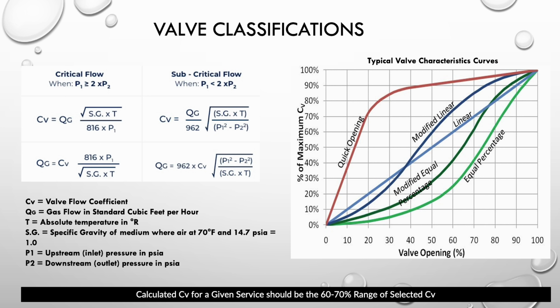Subcritical flow, which mostly you're going to see in liquid flow. Again, liquid flows can still have sonic flows, but for it to reach that point, the pressure drop has to be significantly high. It's something you wouldn't get accustomed to seeing in industry. So normally speaking, liquid flows tend to be subcritical 95% of the time. On the other hand, any gas flow that you have to deal with, most likely is going to be the reverse of that. It's going to be critical flow. Well said.